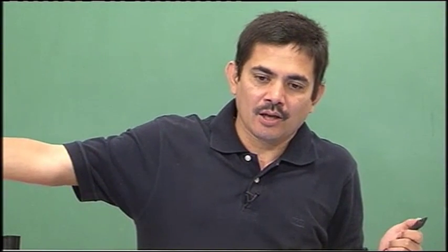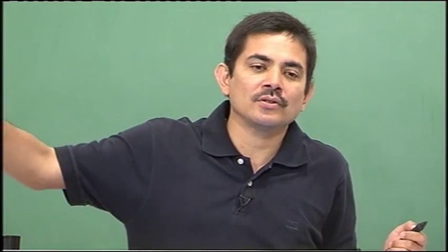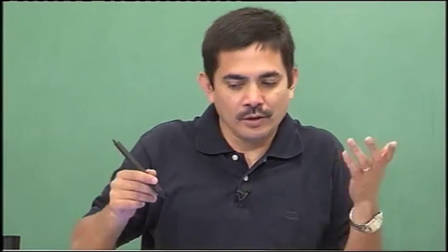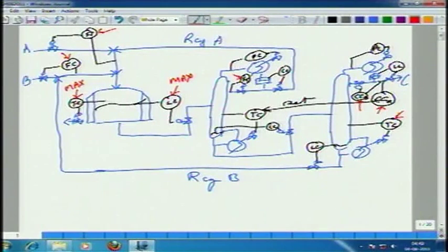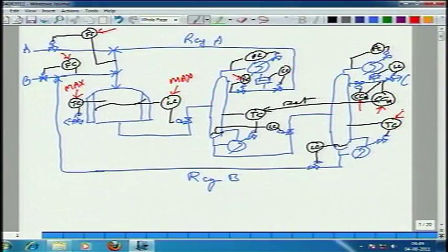Okay. But from a practical standpoint, there are always side reactions, and because there are side reactions, there is a limit as to how much C you can allow to leak out. Well, you allow as much to leak out. See what I am saying? So, you have a way of setting the temperature controller set point 2. In a similar way, the reflux set point also gets set in the recycle column. You can't allow too much A to get recycled, or too much, what should I say, what is the impurity here?